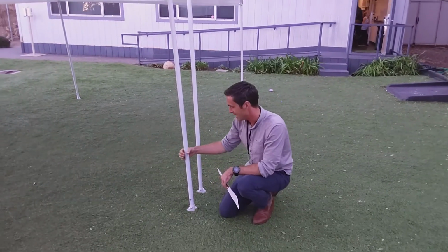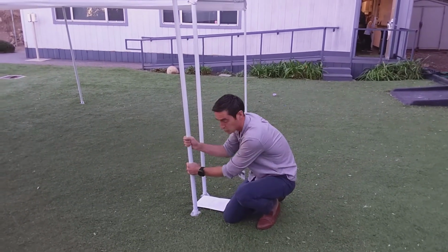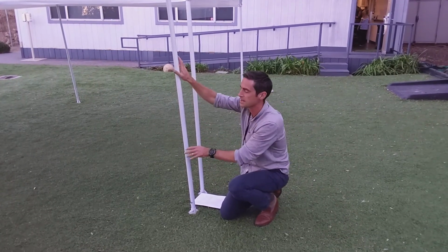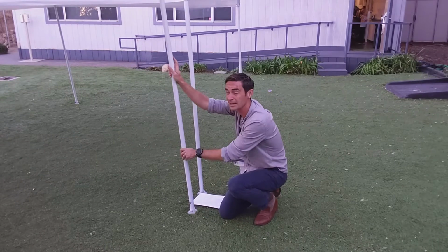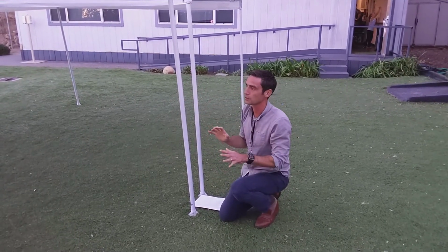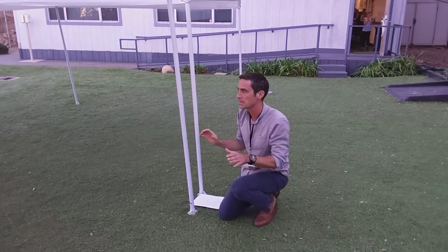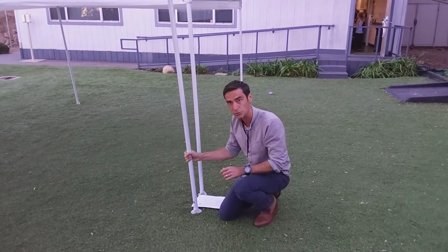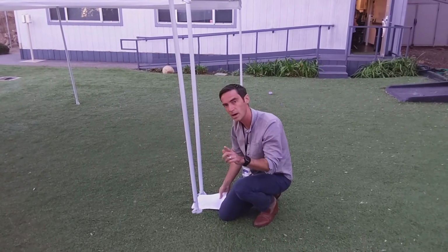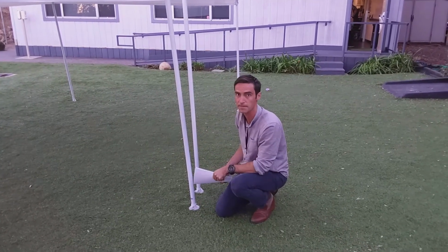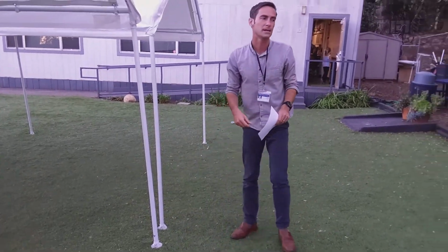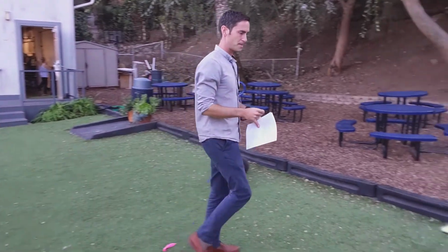It can twist. It can actually, if I push hard enough, it can rotate freely that way, and it can rotate freely this way. Okay? So it's free to rotate in all 3. It's free to slide in 2 directions, but it cannot move vertically. That's the one way in which it is constrained. Okay, this is called simply supported. Let's go on to another kind.